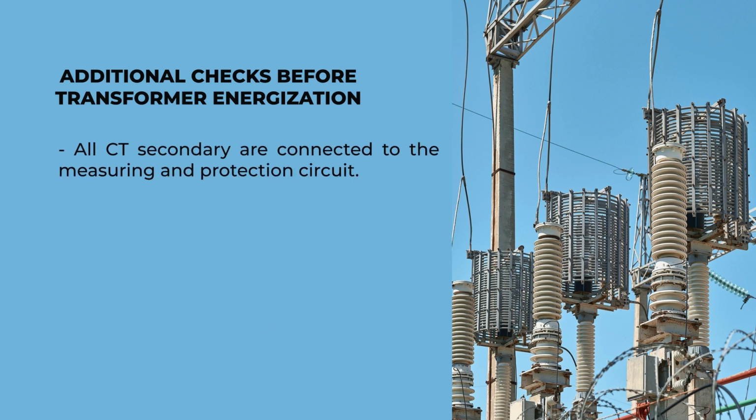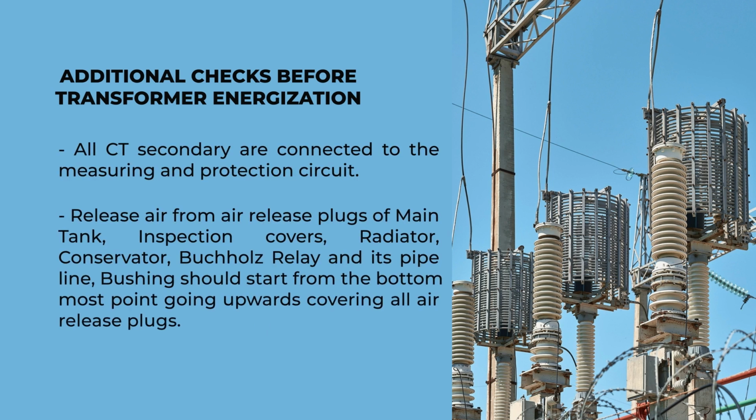All CT secondaries are connected to the measuring and protection circuit. No CT secondary should be kept open. Otherwise, a high voltage on the secondary side can take place and it can damage the CTs. Therefore, you have to see that the CT secondary should not be open.